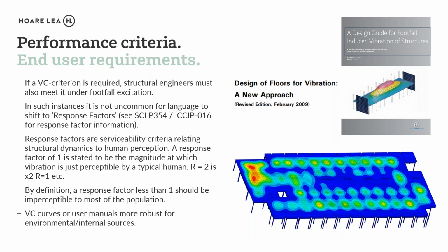And it's an honourable mention for structural engineers and how VC criteria affect structural design. Now, the common language for a structural engineer is to speak in terms of response factor. Response factors are a means of describing floor serviceability, how the floor feels under footfall excitation.